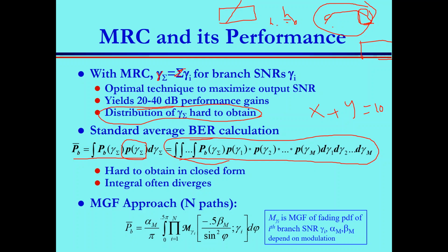So the problem turns out to be h1 plus h2 plus the data equals 0, you force it to 0. So your design problem turns out to be: what are the coefficients that I need to put on top of this packet so that when it passes through the channel, it becomes the negative of this signal and then cancels to 0? This is the beauty of math.